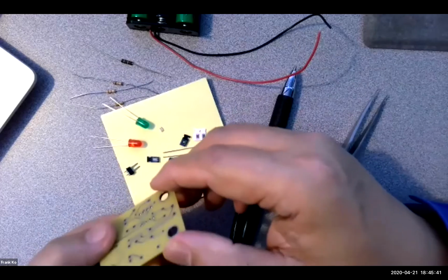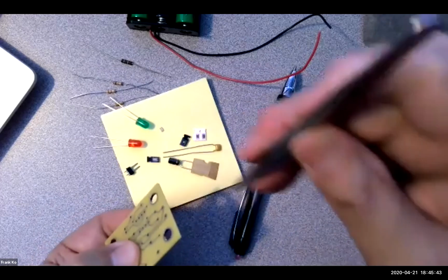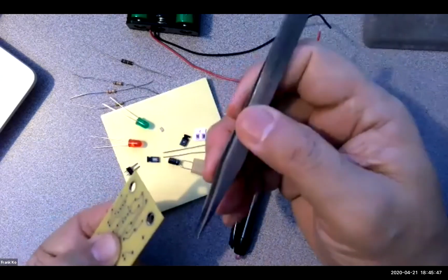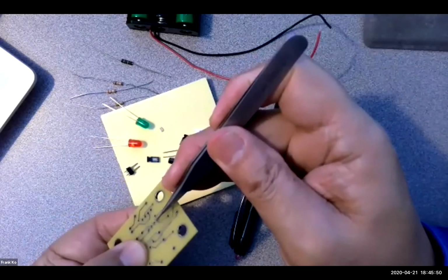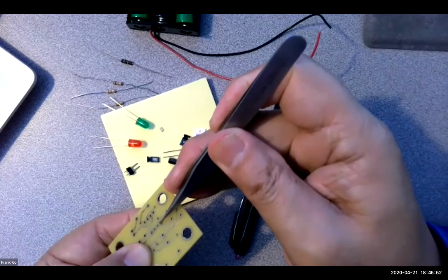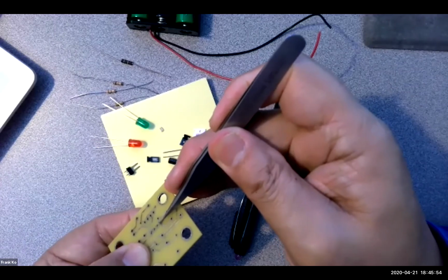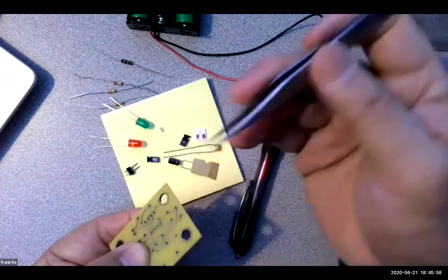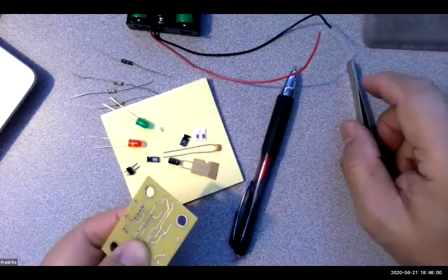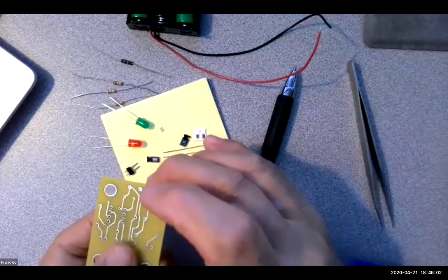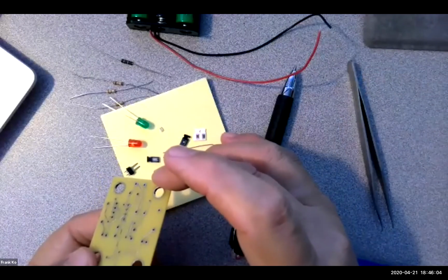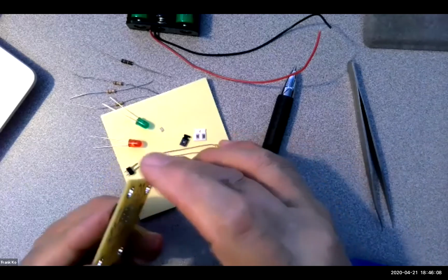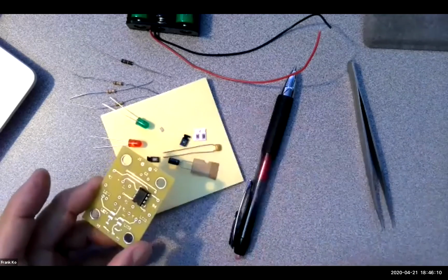Okay, when you do have the chip in place and the proper orientation and you're ready to solder the pins, remember, because you're soldering the chip directly, you don't have the benefit of a socket in this particular case. You're going to use just enough heat on the pin and the trace to heat it and take the solder and immediately go to the next, go to the next, go to the next. Don't leave too much heat on the pin, otherwise you'll burn out parts of the chip. Any questions about the chip, its orientation, and what concerns we have about soldering it onto the board?